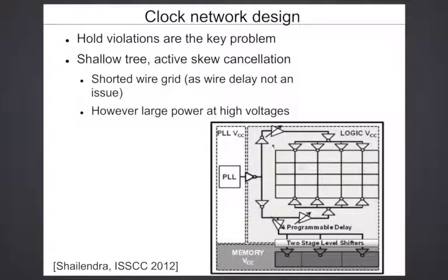lower power. So now when you come back to this particular design, which is giving you low skew at low voltage, maybe the clock power might not be that much of an issue at sub-threshold. But if I want to make the same chip operate even at high voltages, then is this the right way to do it? How do I design a chip where it can work well at low voltages as well as at high voltages? Maybe it is not optimized for the highest voltage, but it's also not too bad. That is definitely a challenge as to how to do it. So that's not clear yet.